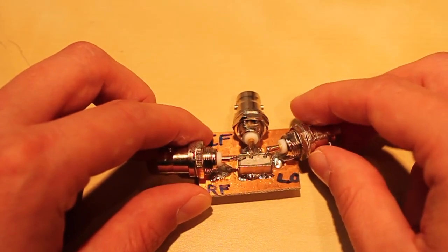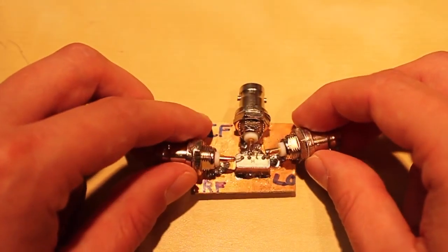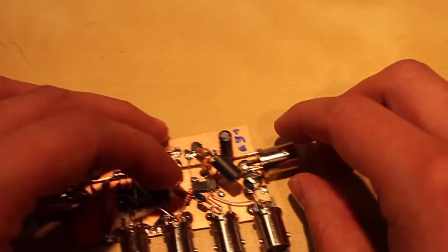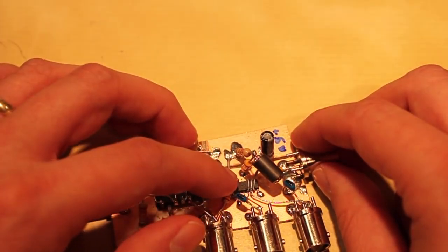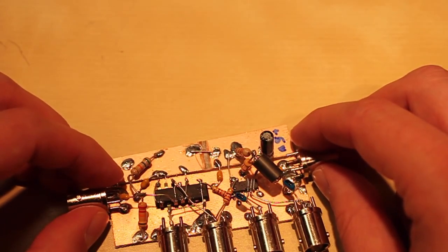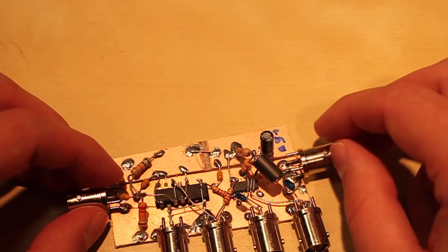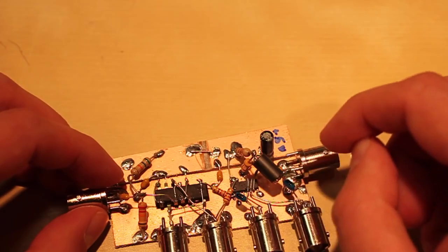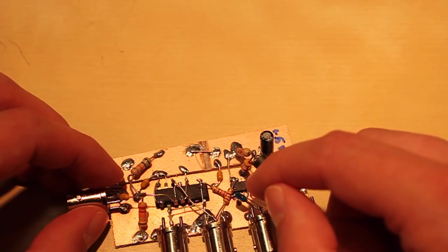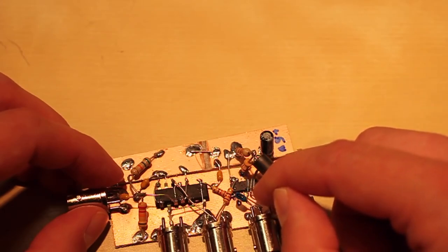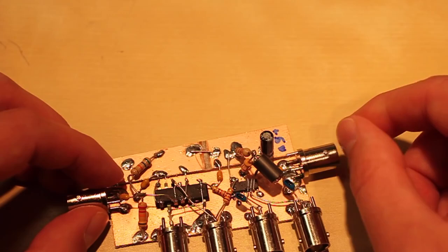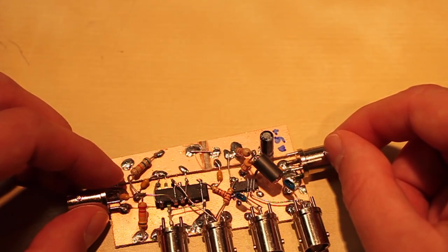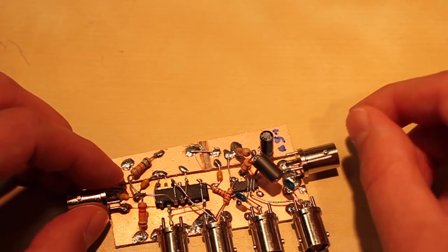So for most implementations of quadrature mixers, at least in homebrew equipment, you'll find them using these little 4-to-1 multiplexer ICs instead. And these are commonly referred to as Tayloe mixers after Dan Tayloe, who popularized the idea. And it's really very clever because you only need 1 of these chips. They're very cheap, about 50 cents a piece. They require very low local oscillator drive levels, so you don't need a lot of power out of your local oscillator. And they still have a nice high third order intercept, so they're still fairly immune to being overloaded by strong signals. And on top of all that, they have very low insertion loss, less than 1 dB.